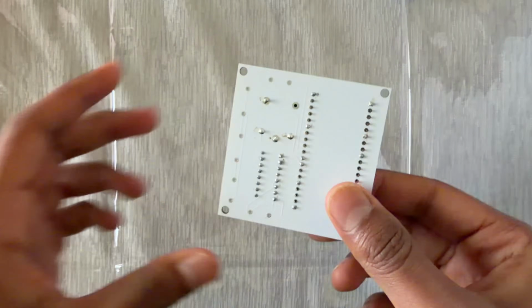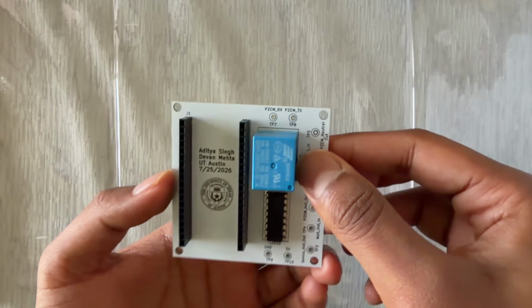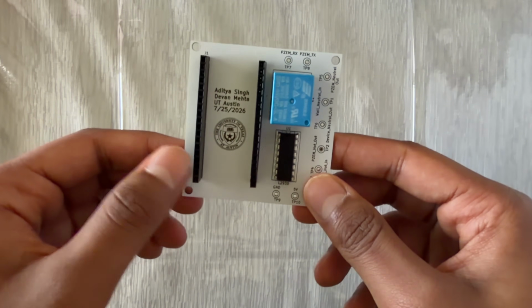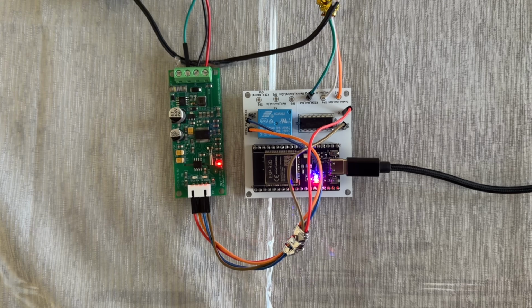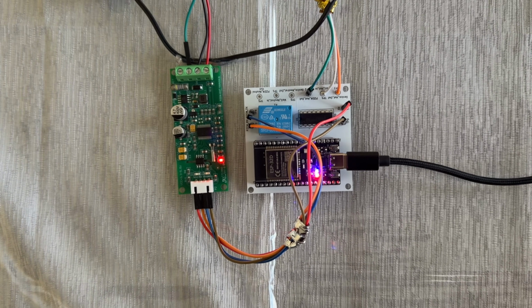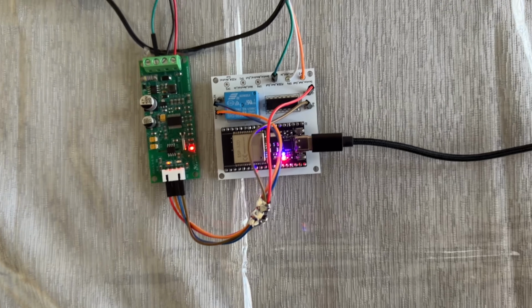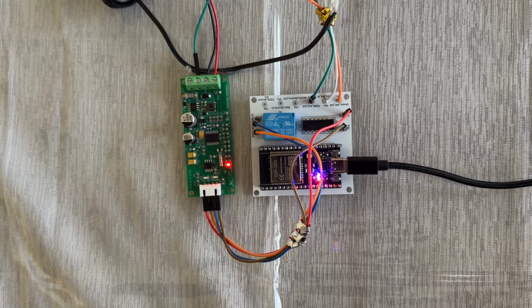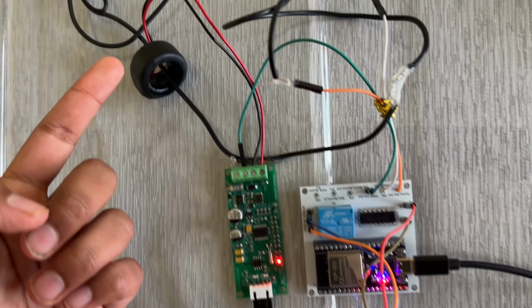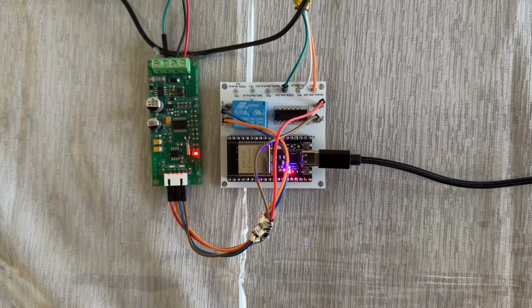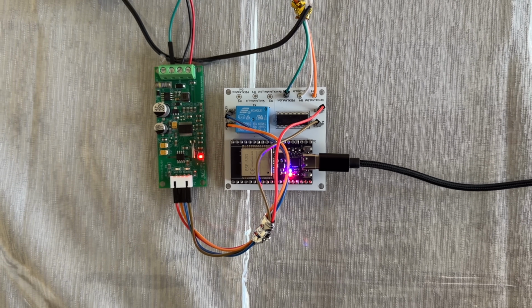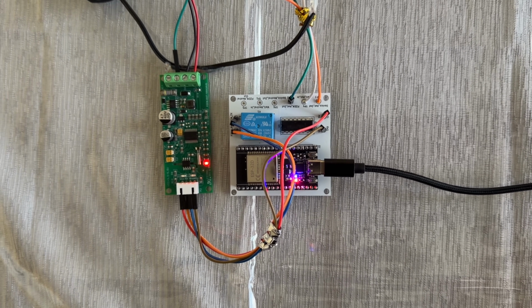So this is the PCB that we designed for this project. It includes a slot for our ESP32, a relay block, and an L293D. So here's the PCB and the PZEM004T with our load device. The load device has a hot and neutral wire. We monitor the neutral wire using the PZEM clamp, and the PZEM translates the readings into numbers that ESP32 can read through the use of UART with Modbus RTU protocol.